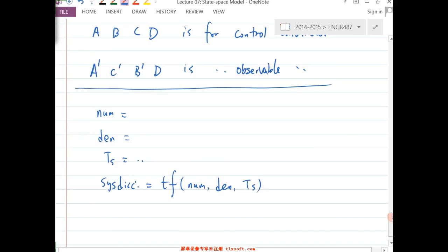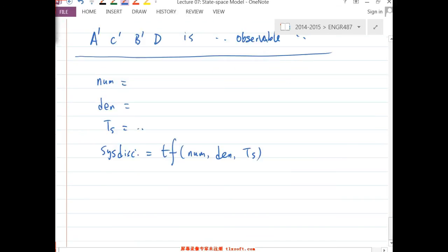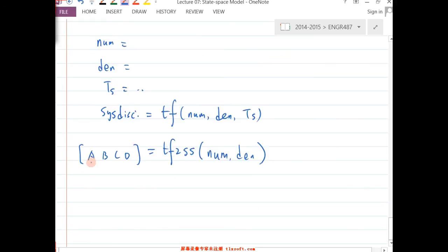And then in MATLAB, there's a command called transfer function to state space. That function takes the numerator and denominator and returns this A, B, C, D. If you check the default, the A actually is a control canonical form from this function.